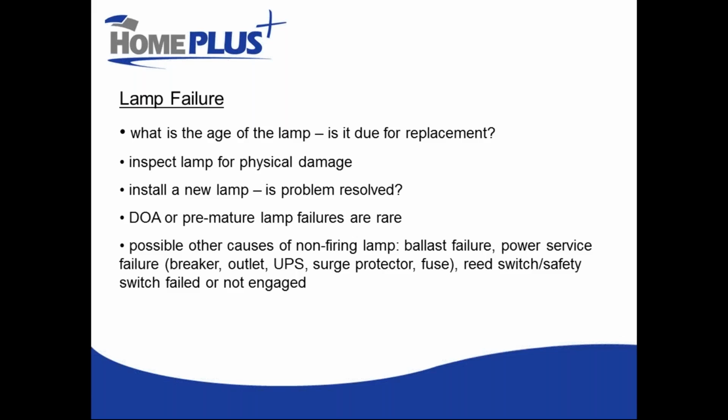You could just simply reverse it and use the other reed switch that's built into your system and see if it fires with it flipped around the other way. Now you do have to take your sleeve bolt and turn it 180 degrees to do that. But it's very, very easy to do. So you basically have a built-in backup without really knowing it.